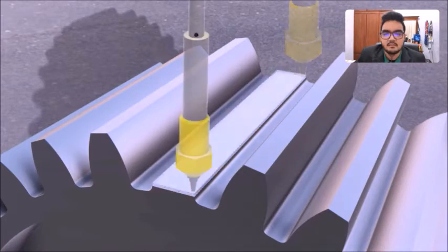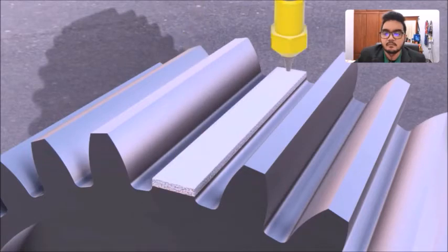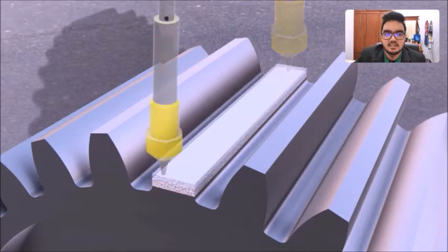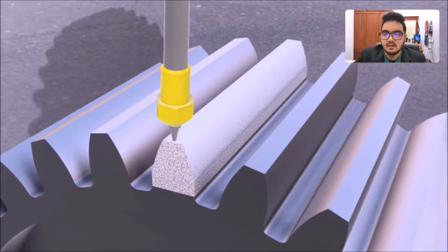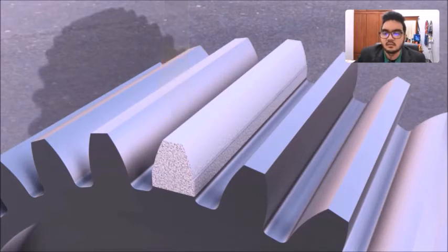The LMD extrudes metal onto the surface, and the movement is controlled by G-code generated based on the shape of the teeth. The LMD creates the exact same shape of teeth as before, thus reducing any material waste. The new teeth is now created, but it needs finishing by sanding off excess material for a much smoother surface.